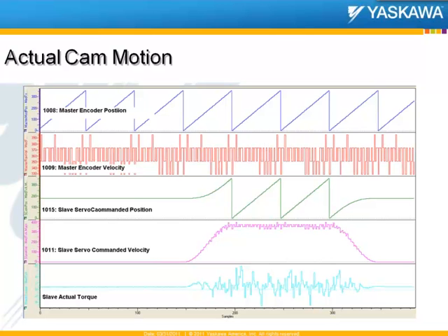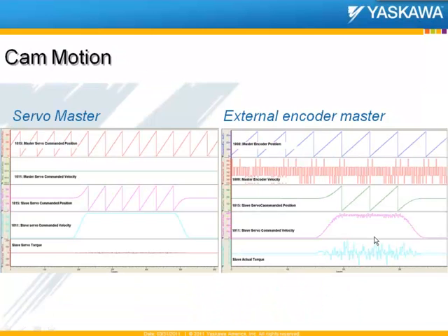And usually when a servo generates noise, or if the torque curve looks ripply like this, people immediately start thinking, oh, I need to tune the servo slave. I need to tune my servo axis. But that is not the solution, because if your master signal itself is not clean and filtered, then even if you tune the slave tightly, it is basically trying to follow this rugged landscape of master position or master velocity.